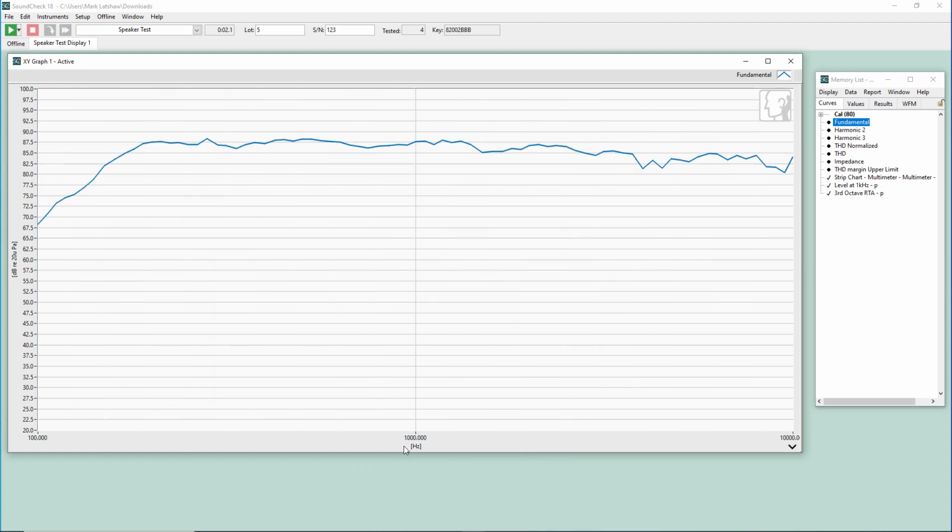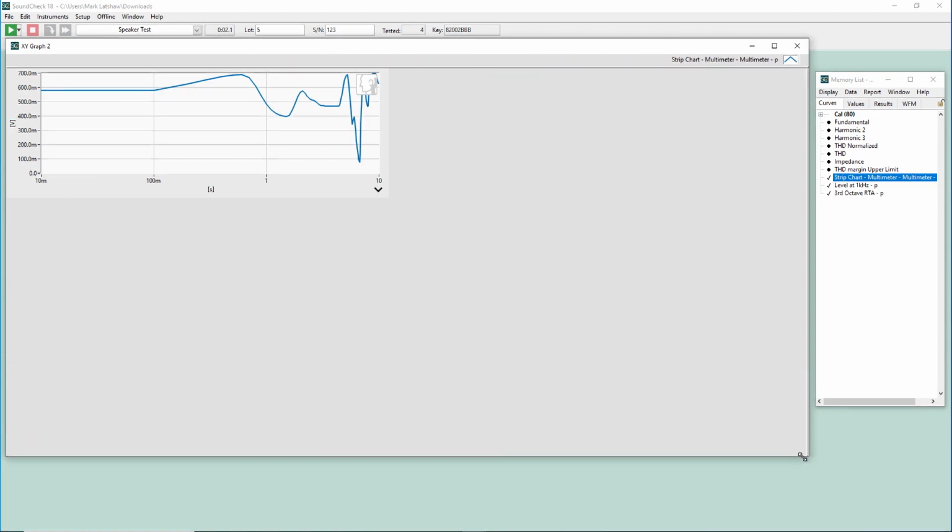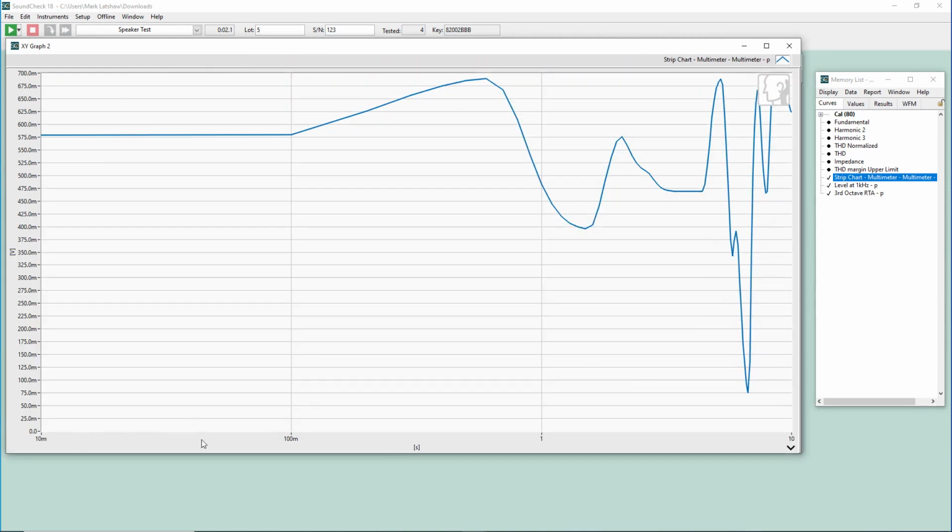A common use case of this would be using the strip chart recorder. The strip chart recorder will output a curve even though the x-axis is time-based. If in the strip chart recorder I defined to output absolute time, I would want to change the x-axis to also graph in absolute time.